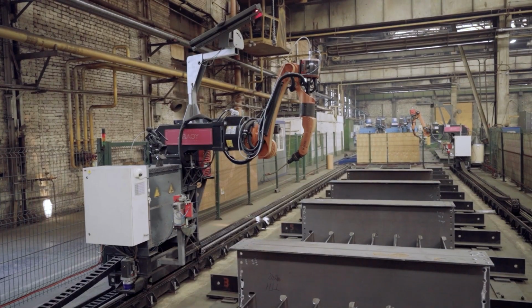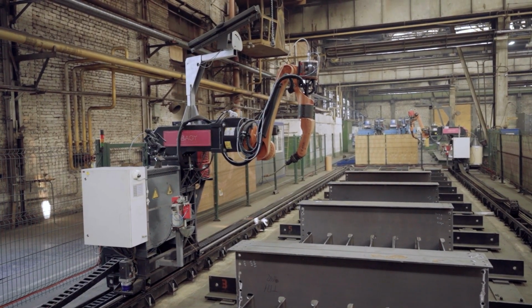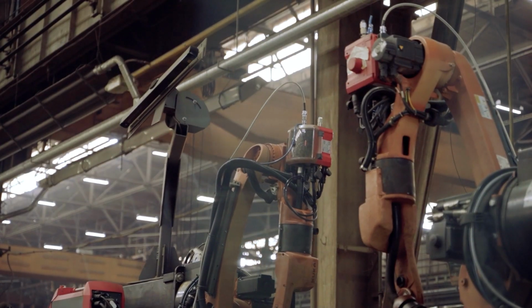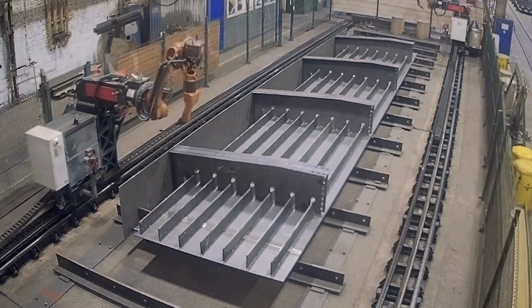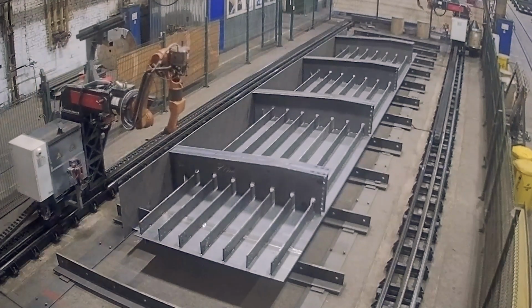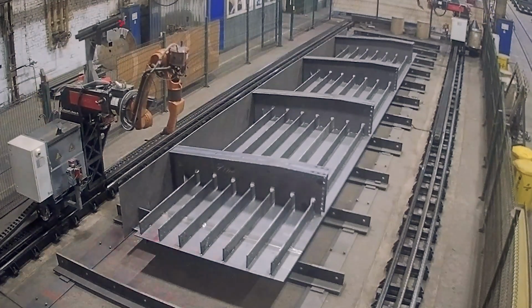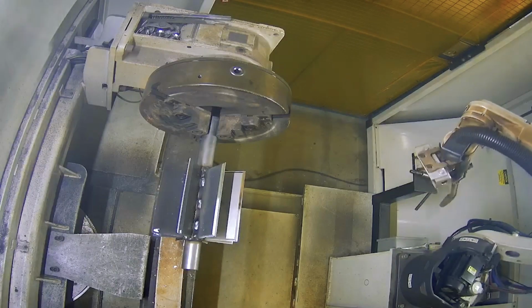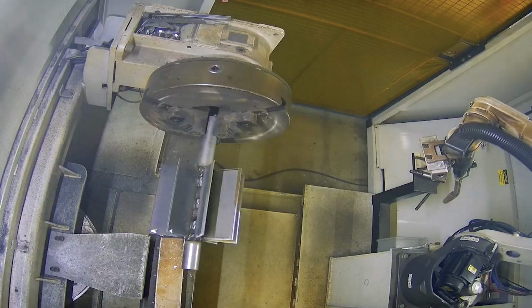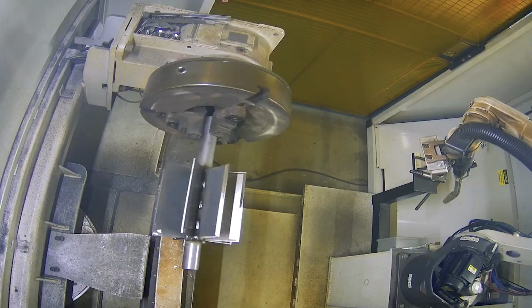Also, it depends on the size of the parts you work with. For example, if you have parts several tens of meters long, then you probably want to make as few shots as possible, so you had better choose a larger field of view. And if you have just small objects that you want to scan, you can use a smaller field of view and a smaller scanner. And as I already said, it all interconnects with the accuracy.